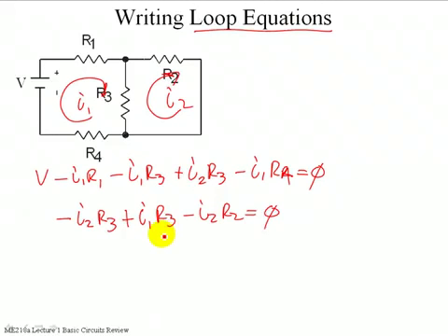What happens if I go through and I calculate that I2 is minus a half a milliamp? What has that told me? Pardon? Yeah, if you end up calculating a minus value for the current, that just means that the direction of the arrow that you assumed was wrong. Current's actually flowing the other way. Perfectly valid result.